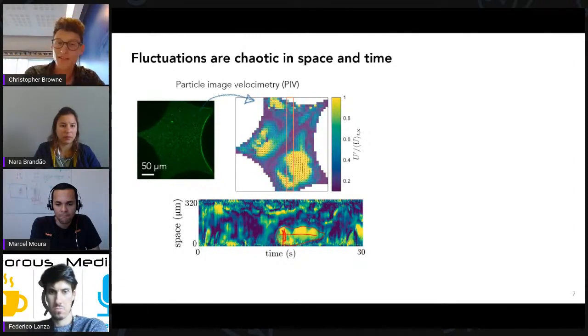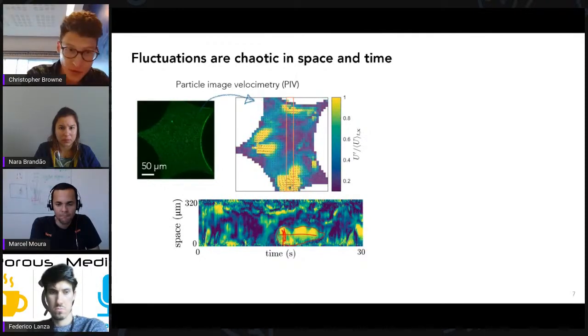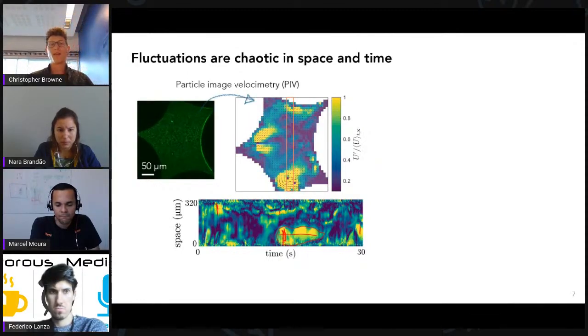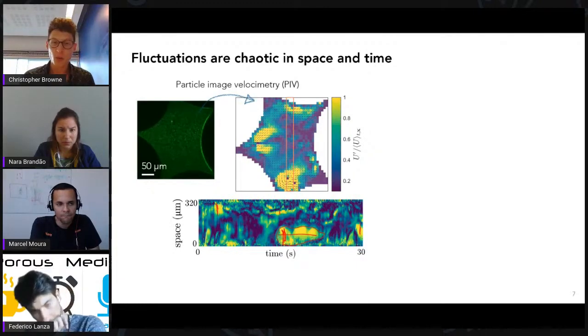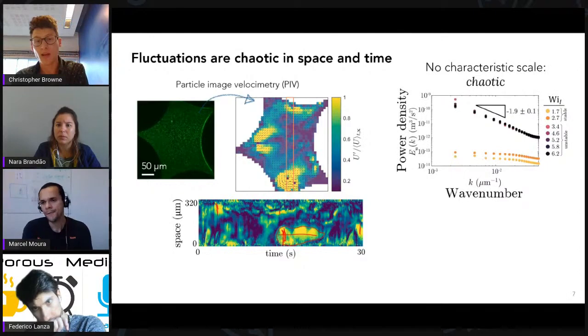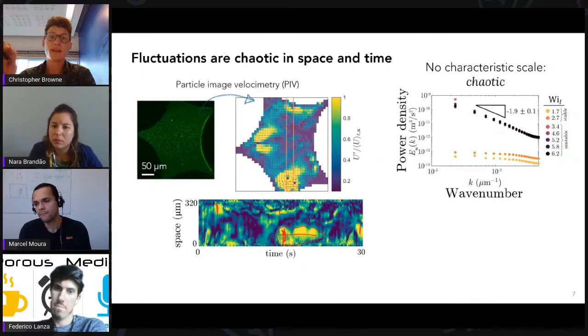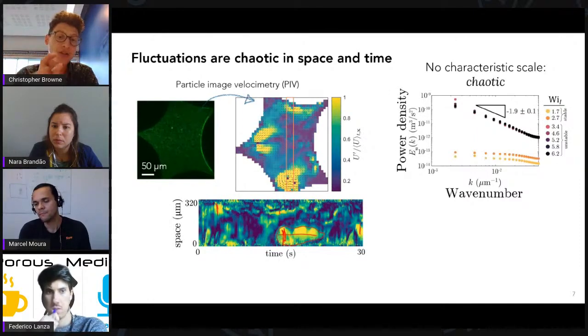What you might first do is ask, is there a characteristic size to these bursts? Essentially you could just draw a bunch of these by eye and do a histogram. The more rigorous way to do that is to do a Fourier transform of this. And what that gives you is an energy spectrum. You can think about this a little bit like a PDF of these burst sizes, but I've done some prefactors and a squaring of that to give you what is properly an energy density. So you can think about this also as the energy contained in flow structures of a given size.